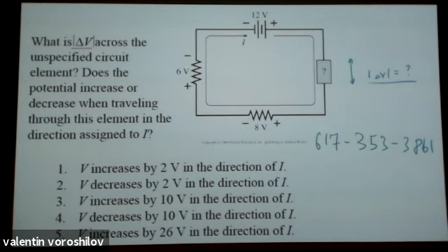Thank you. That is absolutely right. So very, very quickly, let's do it again, because the strategy is the same. The lowest potential set to 0, and the wire does not change potential. Potential up to here is 0, but potential changes by 6. So 0 plus 6, that makes this potential 6 volts, and wire does not change potential, so 6 volts remains up to here.